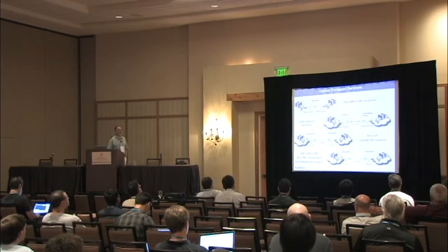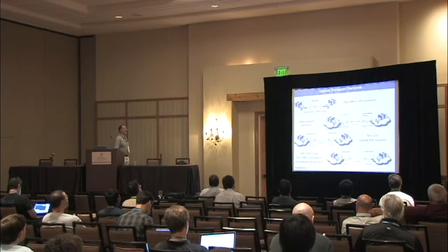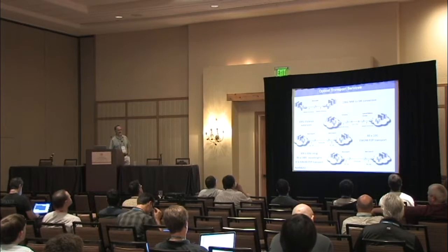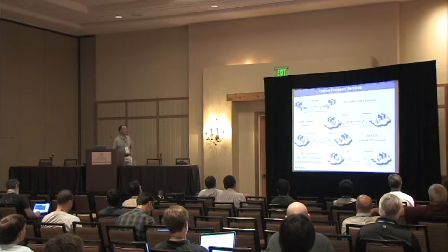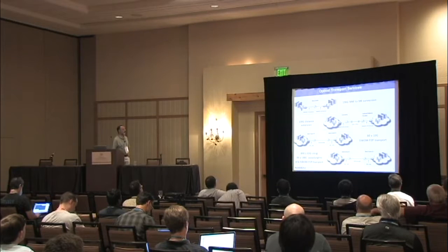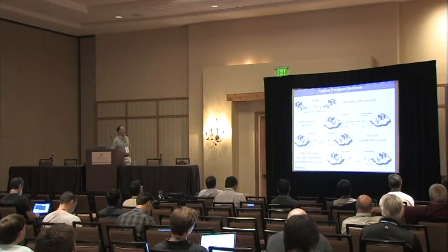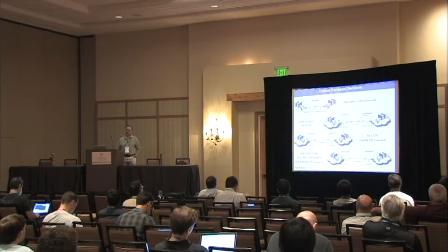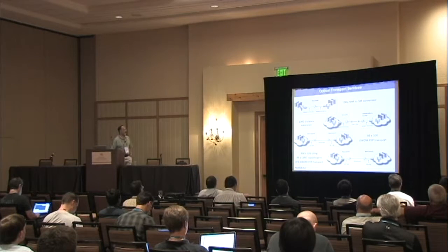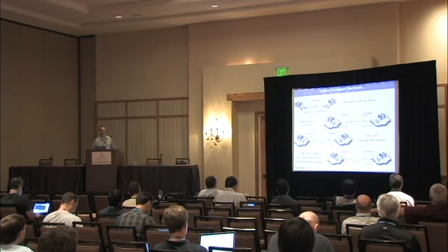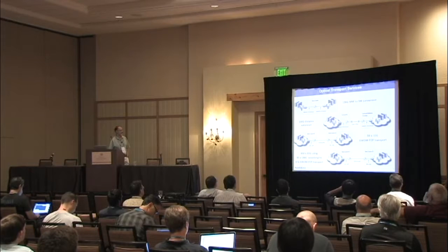So a couple of transport services, and by chance I had the figures for 100 gig, but it can be any rate, it can be 10 gig. Starting with simple media conversion, because that can be very common in your applications. You have two sides: multimode on one side and single mode on the other side. You must convert from one to another. So you basically must put a multimode to single mode conversion on the multimode side and go all the way to the other side. Same for distance extension. You have two multimode interfaces and a long link that goes beyond the reach of the multimode. You must have a media conversion from multimode to single mode and then do distance extension.